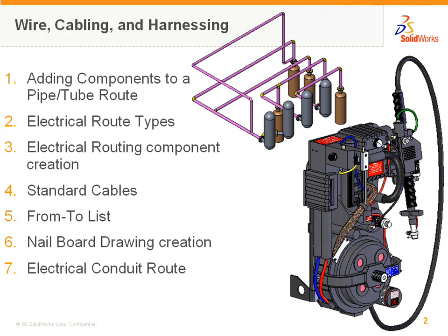The thing that's going to be different than the last webcast is the fact that these routing components for the electrical, they require a 2D drawing block for use in the schematic drawing. Therefore, when we're generating that electrical routing component, it's going to generate that block for us, which makes that portion of it really nice. It used to be quite a pain to pull together.